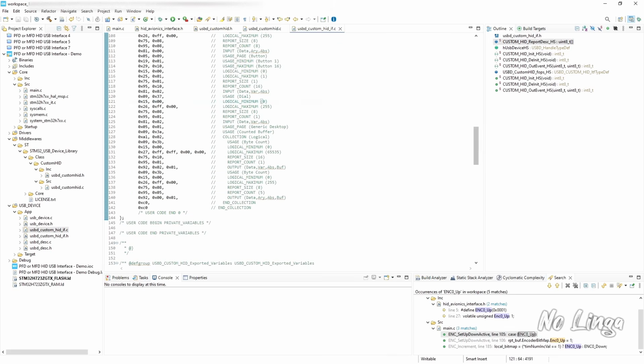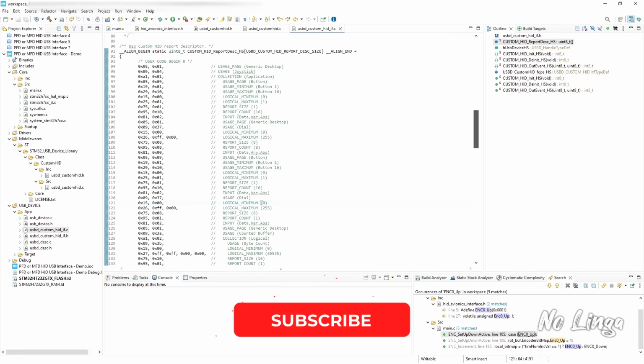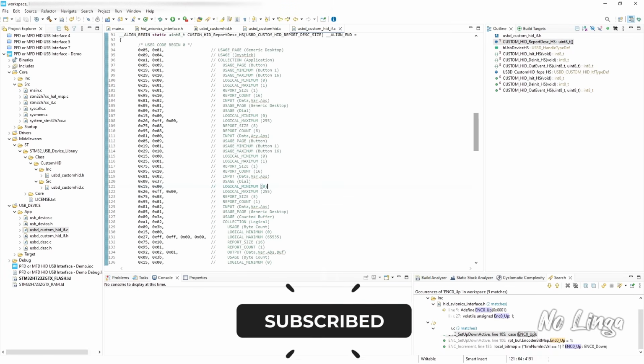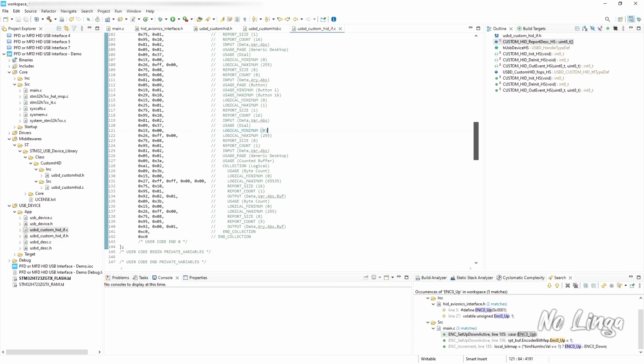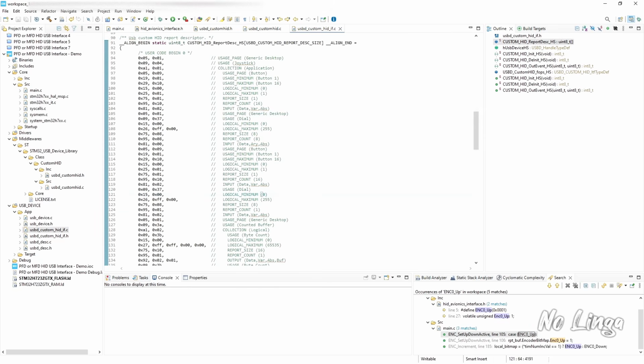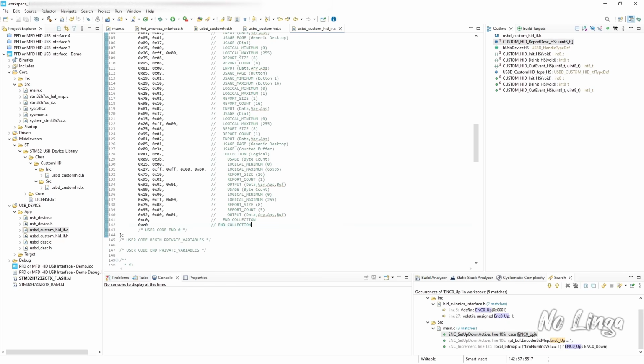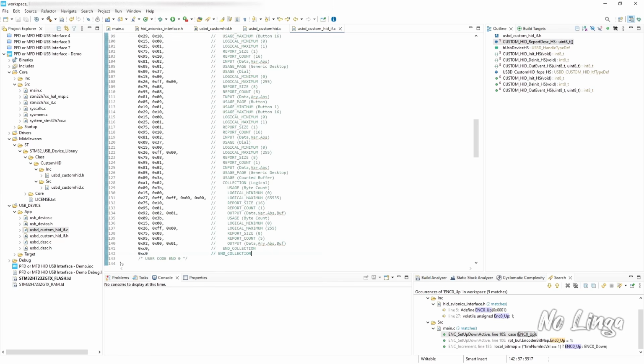But for right now, I'm sharing this. So if you're using it for testing, you can go ahead and look at this, and I'll scroll down so you can capture the end of it as well. So that's how I was able to define the HID report descriptor. Please note that once you change this value, the length of your descriptor will change. So if the length of your descriptor changes, the other values will change in your code. And I'm going to show you where you have to also make a change as well.